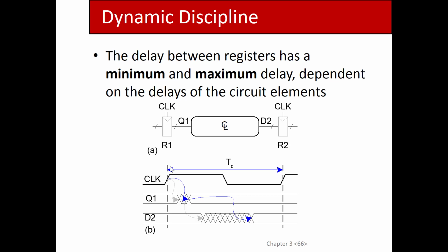So within that cycle, rising edge to rising edge, you have to add up the propagation delay of the memory that's feeding the data path, the combinational logic, and make sure that gets done before the setup time for the destination memory.